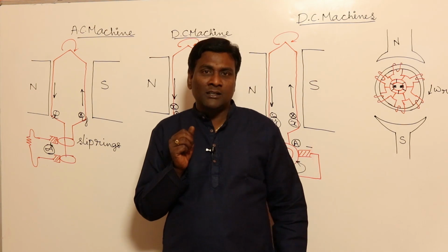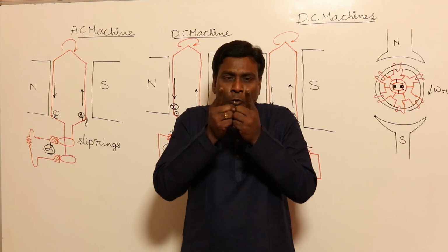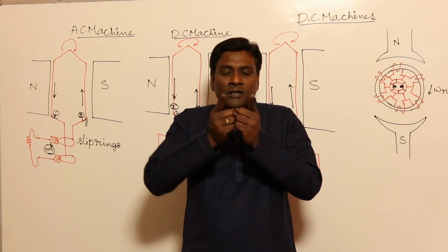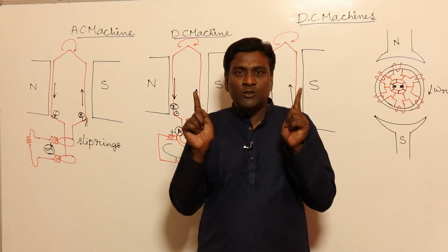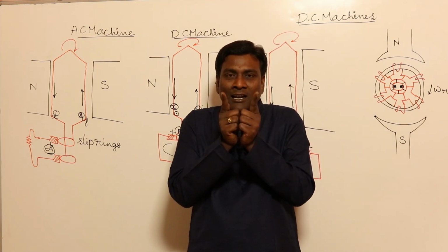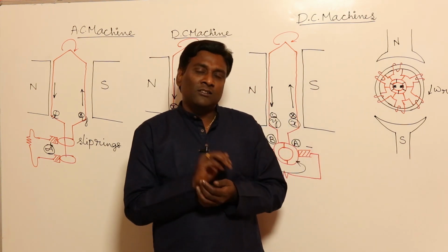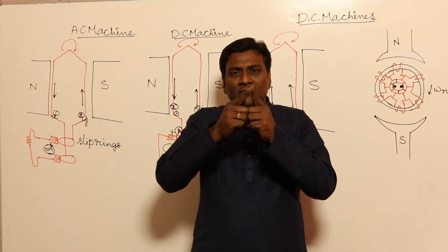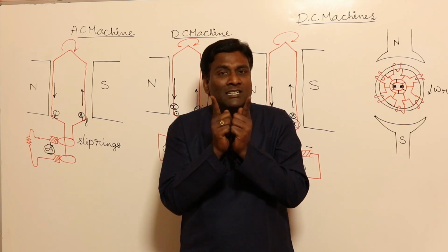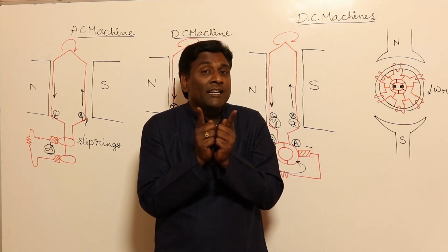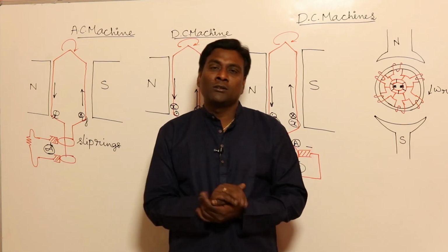Not possible, because for example these two are the two terminals. I am about to close the switch here, for example, across these two I have 100 volts. Now what is the dielectric strength of air? 30 kV per centimeter. For example, in between these two, 1 centimeter is the distance. In that, what is the dielectric strength of the air? 30 kV per centimeter. So up to 30 kV, my air can block the voltage.